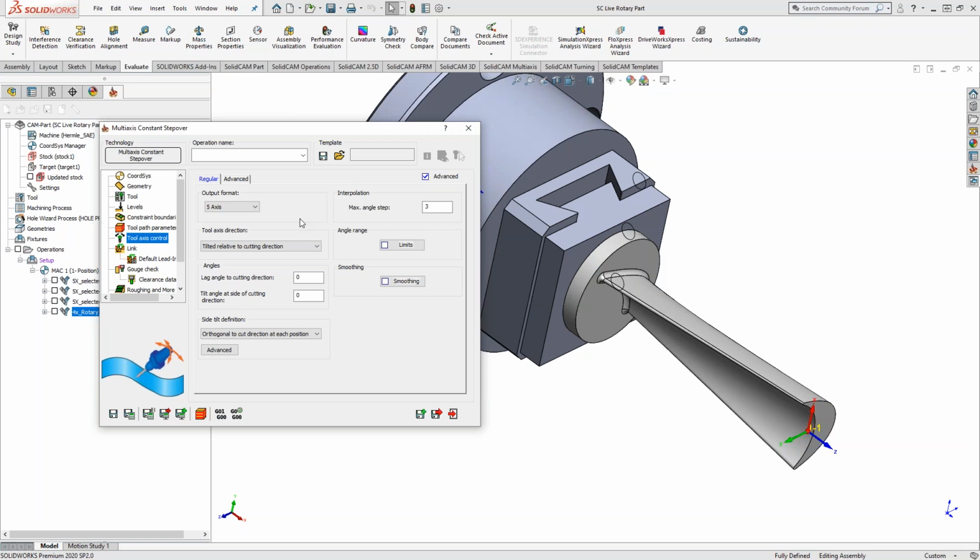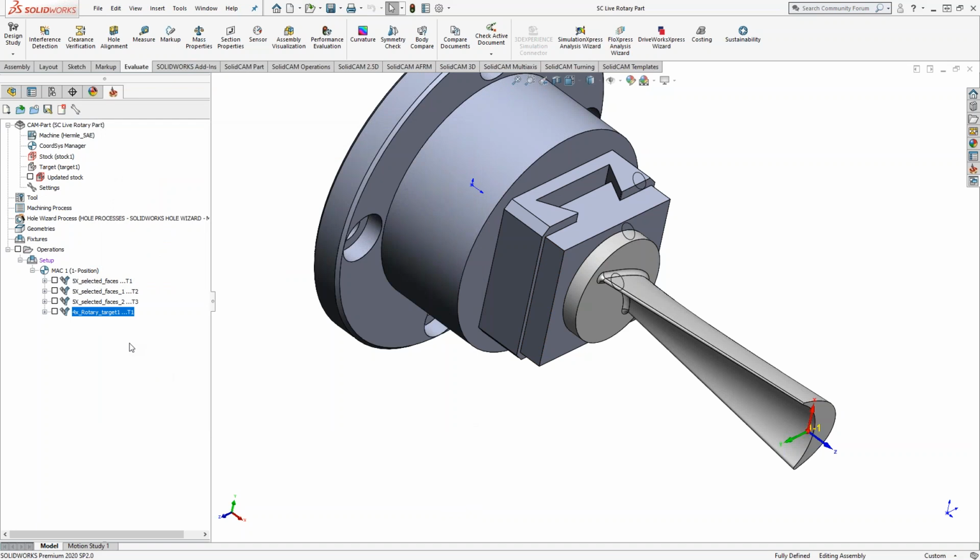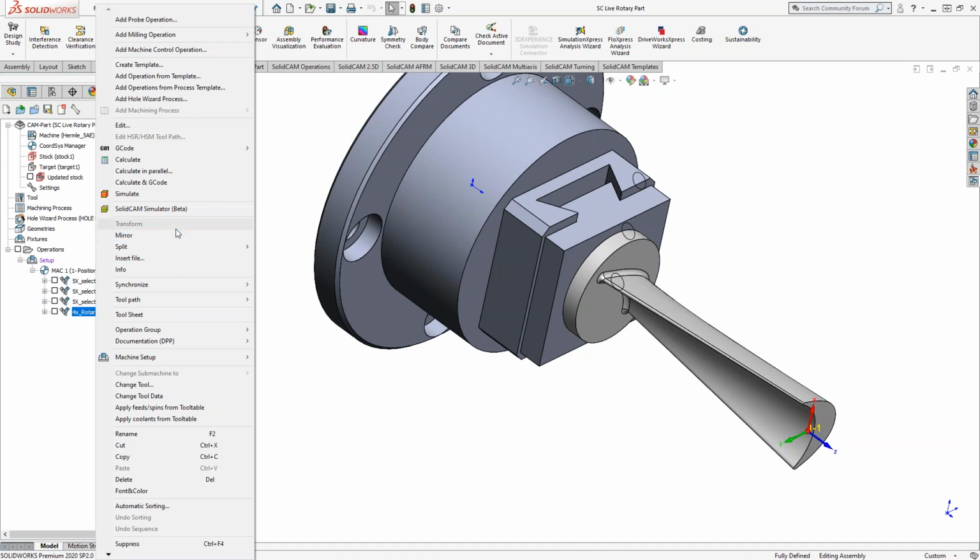He does a better job on the YouTube channel, that our colleague from India. So I can't touch too much on this one, especially since I haven't used this one often enough myself. So I don't really know the ins and outs of each of the parameters. The only thing I've ever actually done is morph between curves, or doing this one here where you can see it actually will do something like this. It will drape the toolpath in concentric offsets. In addition to the fact that it's solid based, there's a lot of gouge checking going on in there as well. So automatic tilting and all that. So I think of it as a solid based 5-axis toolpath.